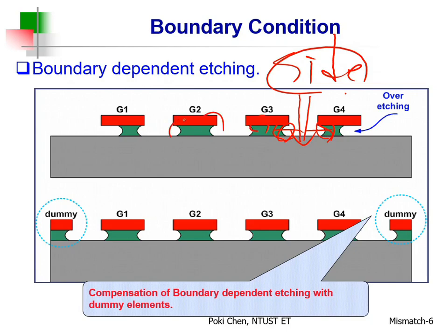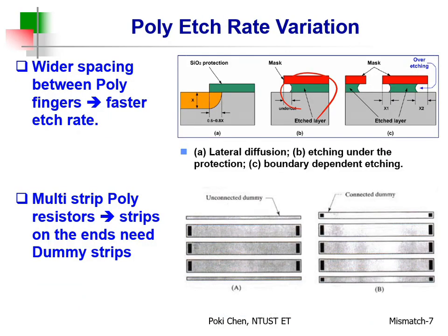Side etching. The edges shrink inward. So the width after fabrication is always smaller than what you plot, what you draw during layout. Okay, but the side etching will become much more at the boundary, so we call it overetching. Sorry, that is for rewording. Let me restate, I used the wrong term. Okay, that's it. Anyhow, even though you are not at the boundary, you don't need to face overetching, but you still need to face side etching. Okay, got it.